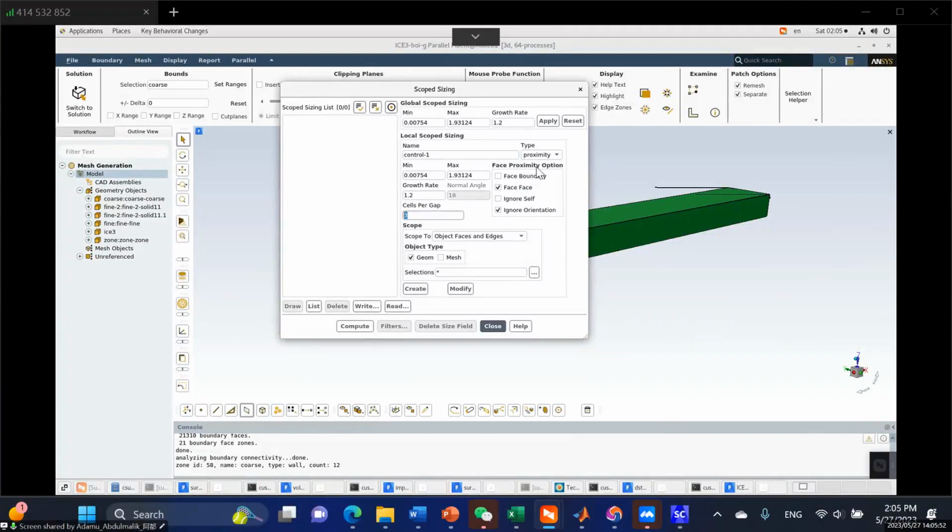We normally use it when we want to mesh the track of the train, because the rail itself is very small. So you say, I want 4 cells on the rail, just 4 cells on a small portion of the rail, should not pass 4 or 5 cells, depending on what you specify.